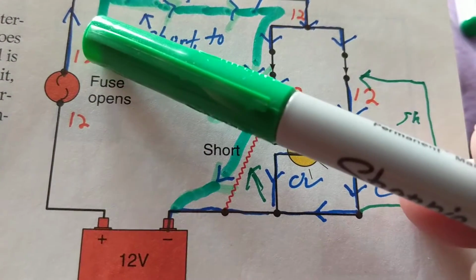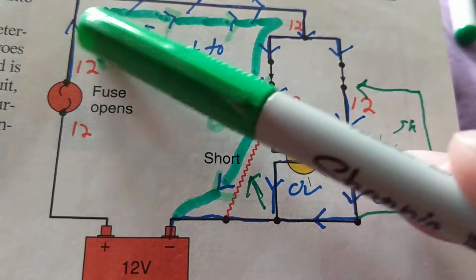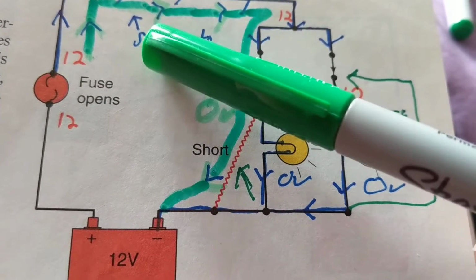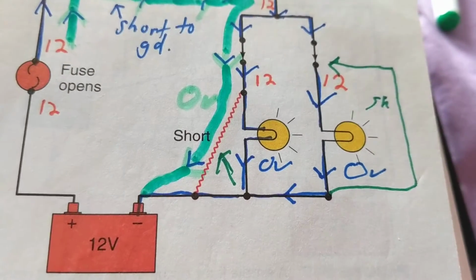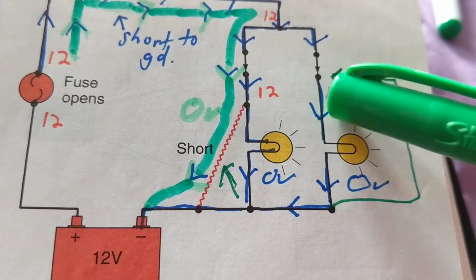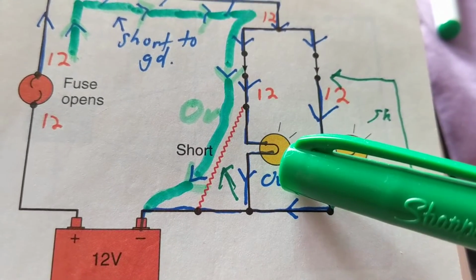Again, we take the ohm meter before we put a new fuse, from here to ground, and we measure resistance. And we will measure very low resistance, indicating what? Indicating there's a short across here or across here, or one of the lights is shorted.